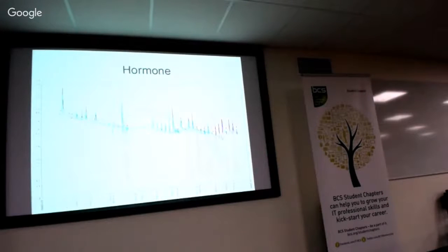So using his little algorithm, he came up with a way of basically, as the battery voltage dropped, so there was less power available, the sun wasn't out so much, you would ramp down the amount of time you spent on, and therefore you would save a little bit of energy. You would also then forward fewer packets from your mates. The other nodes in the network would not be able to send their data back. They try and send you things and you weren't awake as often. So they would fail to send so much data through. So you get a little bit less data, but at least everything pretty much stayed alive.